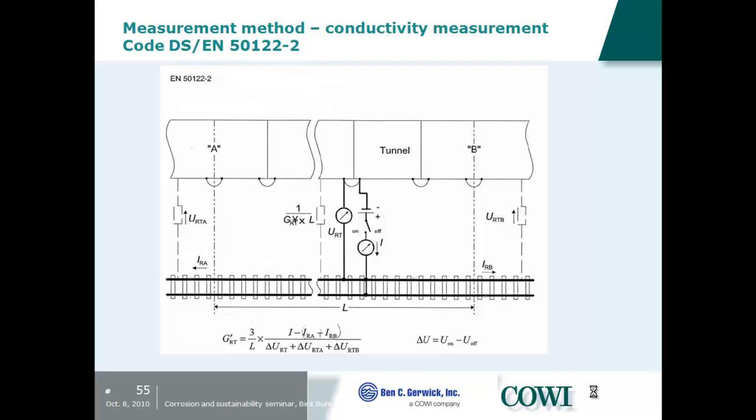Many of our new designs are not with straps here. So if there's a stray current from this system that goes out somewhere in the rail, being picked up in the tunnel, it goes out somewhere, yes, and it would then be the amount of current in the area in here. And you could have the same system here. It could also jump from one to the other. If it does that, you would have a pick-up and discharge, and pick-up and discharge location. These things are very complicated. But by principle, different strategies can be used for doing this.